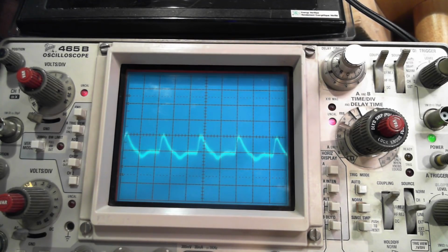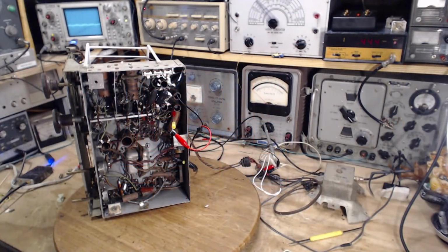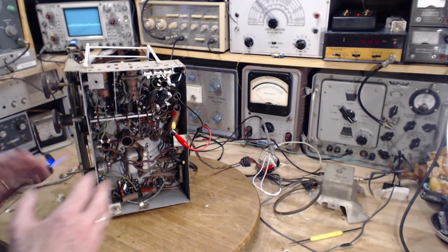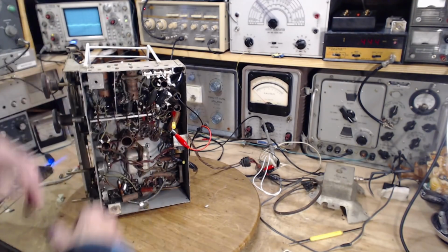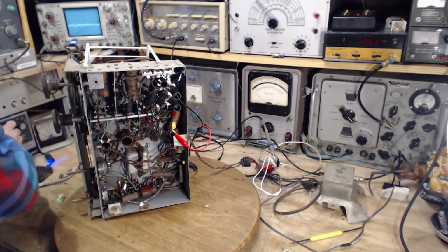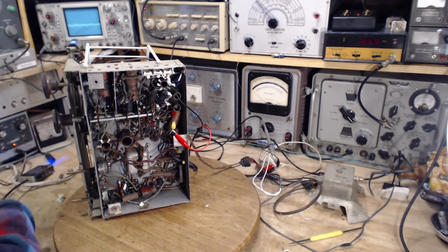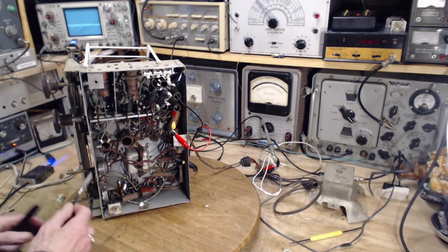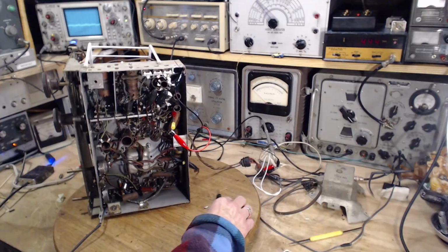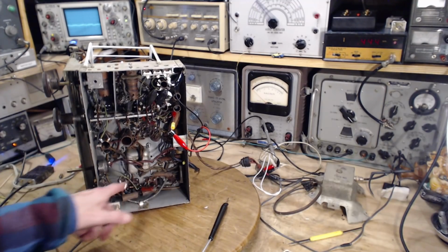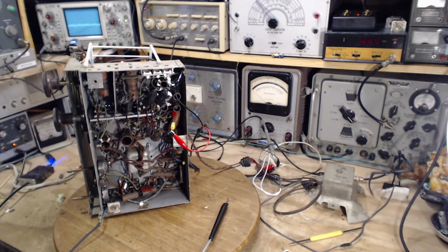Okay, now, with everything like this, we know the radio is now operating in the same inappropriate way it has been. We know the problem is coming from either the IF or the audio. It's almost certainly the audio. We're going to start checking some voltages here. I've got to get that voltage table ready. Yes, I'm chicken. Always chicken. And we're going to check voltages on the two audio tubes and see what we can find out there.